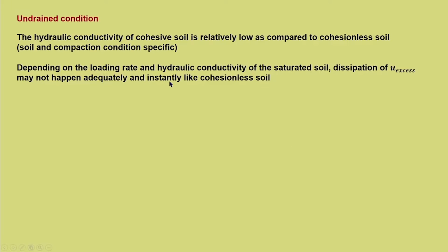Depending on the loading rate and hydraulic conductivity of the saturated soil, dissipation of excess pore water pressure may not happen adequately and instantly like cohesionless soil, which means to say excess pore water pressure is going to remain there. Because of the stiffness, water attracts the load and it holds it.